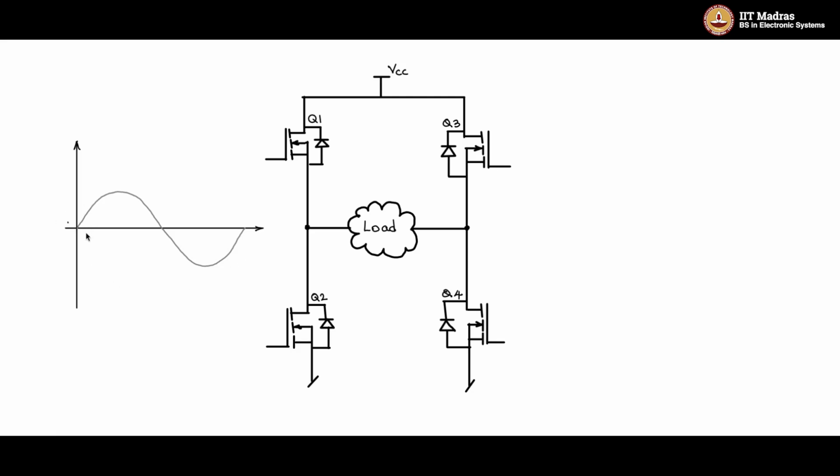And the modulation pattern, so you will see that the modulation pulse width will be lower here because the amplitude of the signal is less, and then the pulse width will be larger towards the center of the sine wave where the amplitude is higher, and then actually gets lower, and once it starts getting to the negative maximum, you will see that the pulse amplitude will be maximum on the negative side. So let me draw this for you so that you get an idea. So you see that the pulse widths are smaller here, and the pulse width is large near the peak.